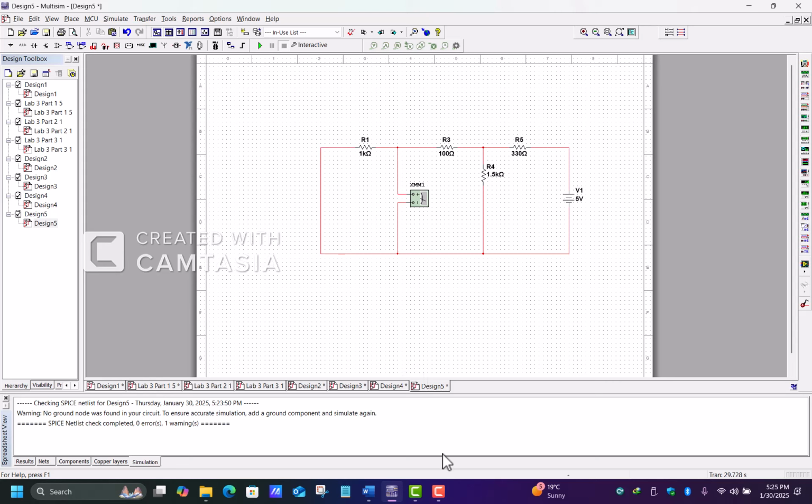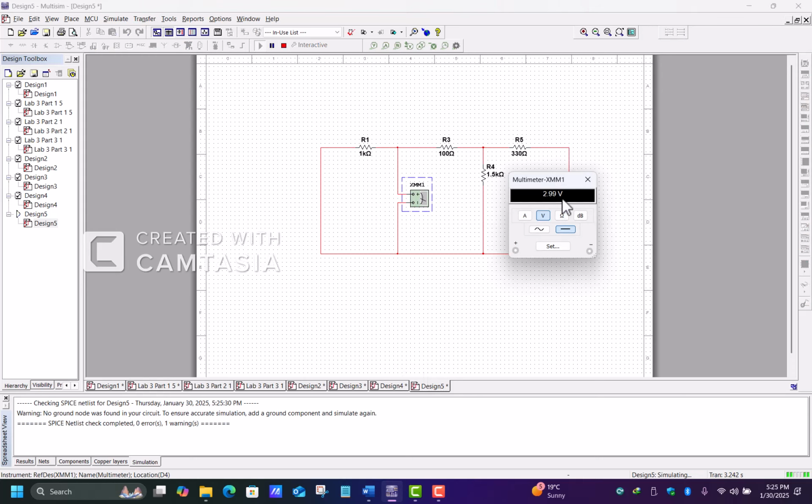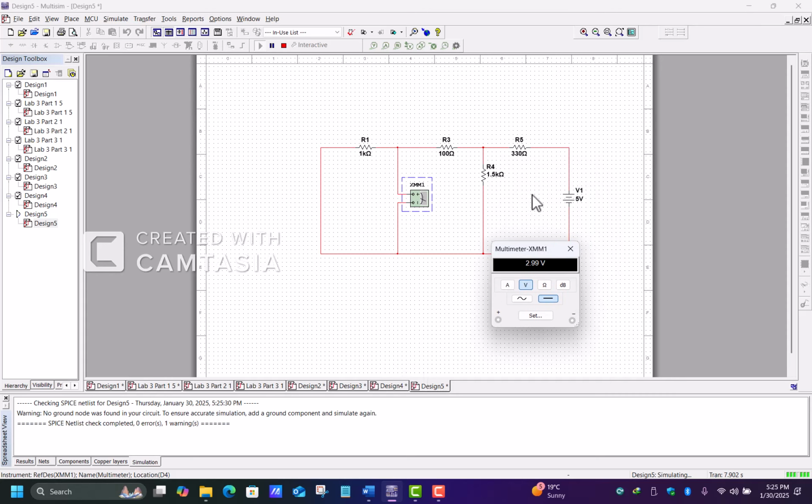So if we put the run button again, we are considering the second voltage source in our circuit. We'll calculate the second Thevenin voltage of the circuit. After calculating two different Thevenin voltages, we'll combine the second Thevenin voltage with the first one to obtain the overall Thevenin voltage of the circuit. So we put the run button now again. This is my second Thevenin voltage of the circuit that I have found here for the 5-volt voltage source.